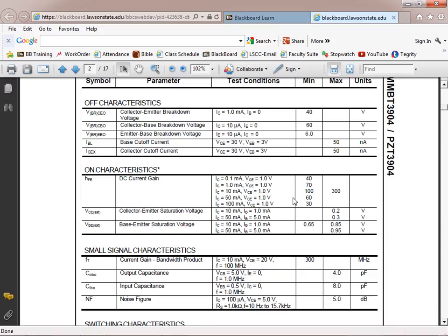You know, I can do all types of neat stuff. I can control a microwave oven with these little old touch buttons on the front. And I can control a lot of power, right? Turning things on and turning things off. But instead of doing it with a switch, we can do it electronically. And we can do it extremely fast. We've had relays around for years. These are electromechanical switches. But the problem with relays is they're slow. And these bipolar transistor switches are extremely, extremely fast.